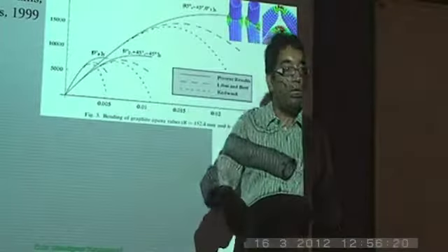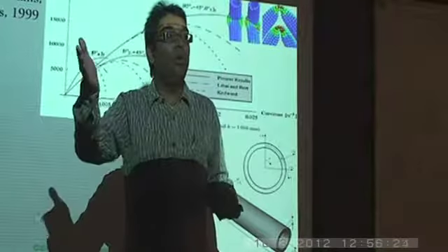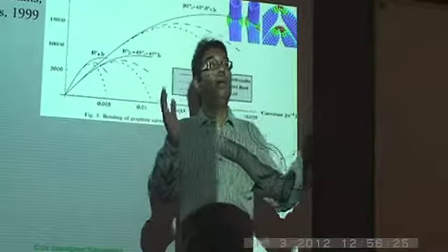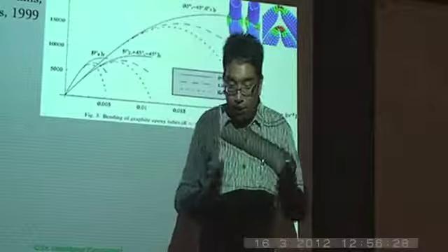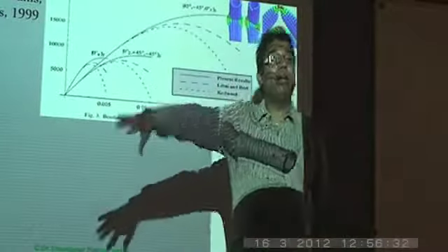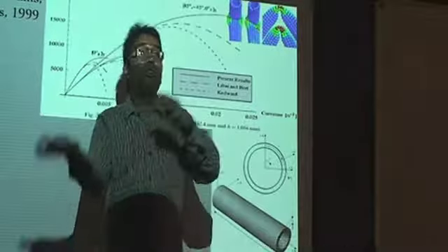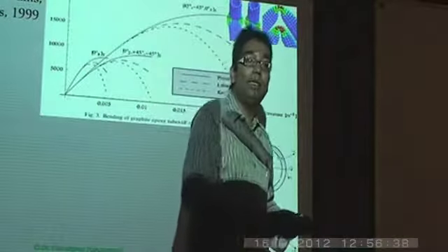And then you solve those differential equations along with the associated boundary conditions and so-called global constraints, because you have to remove the rigid body translations and rotations which are already accounted for. They should not occur again in the warping. So once you do all that, you solve for the warping, you substitute back the warping into the 3D strains.